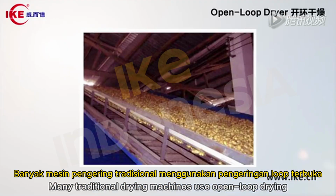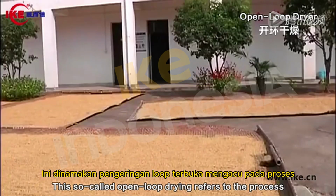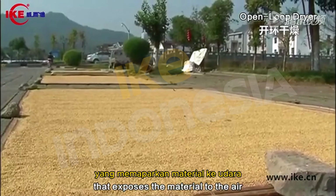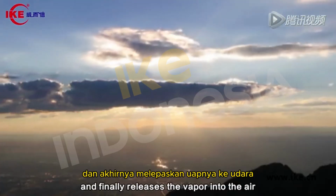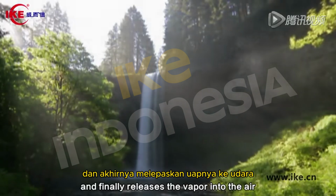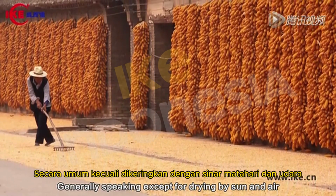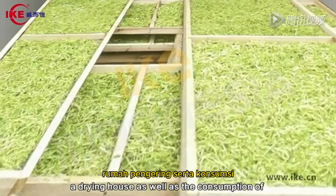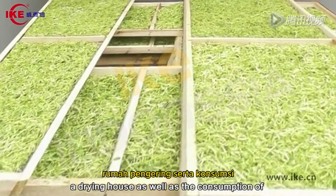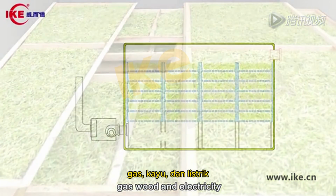Many traditional drying machines use open-loop drying. This so-called open-loop drying refers to the process that exposes the material to the air, uses heat to vaporize water, and finally releases the vapor into the air. Generally speaking, except for drying by sun and air, all other open-loop drying methods require the building of a drying house as well as the consumption of many precious resources like coal, gas, wood, and electricity.